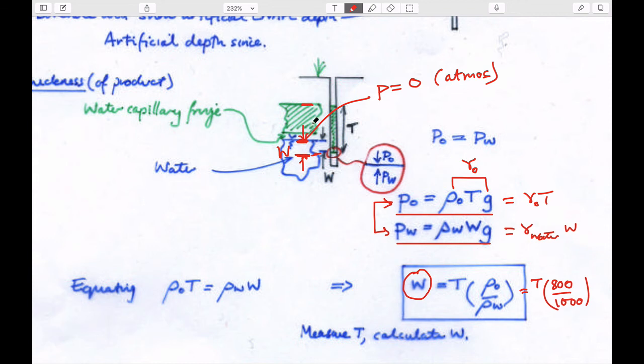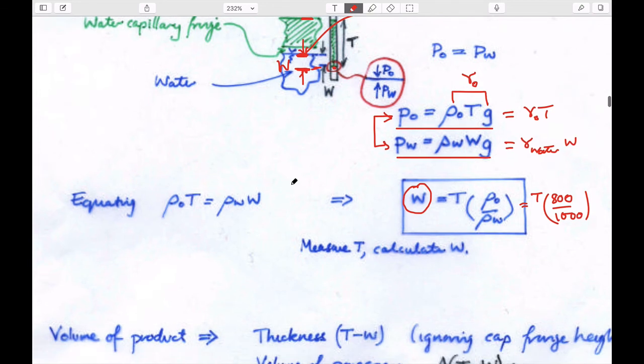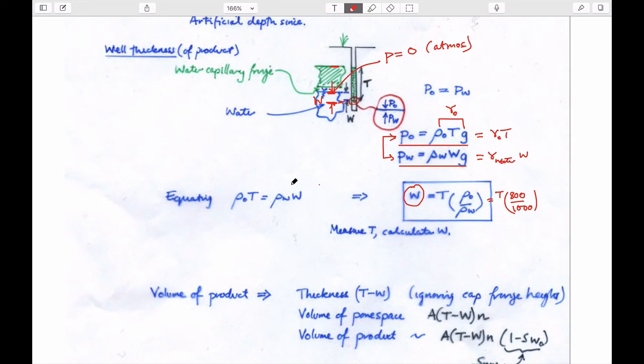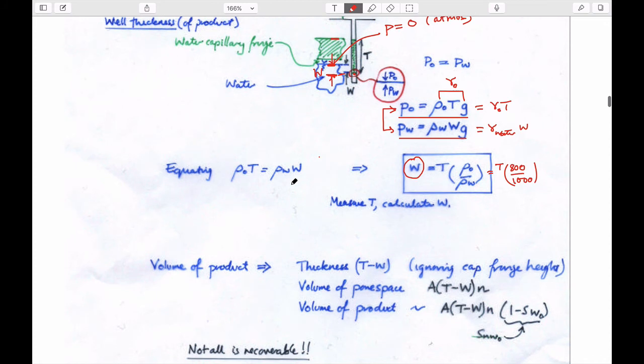And so that's important if we want to be able to figure out exactly how much material there is that we're going to use. And so it's a very simple calculation to make. It only depends on the relative densities of the two fluids that are sitting there. And it is a direct consequence of the fact that we end up with a water table and an oil table. And by definition, since the definition of a water table is where the pressure is zero, we can calculate the pressure of this interface being equal to just the height of this water column. Okay?